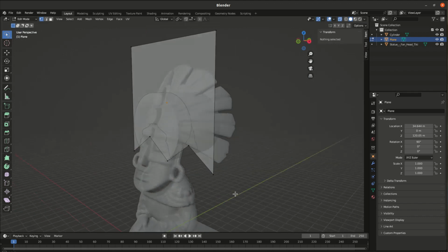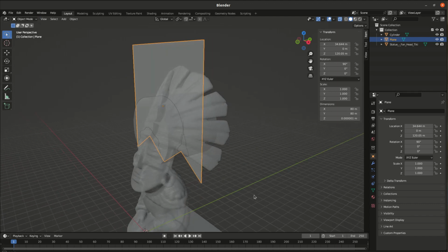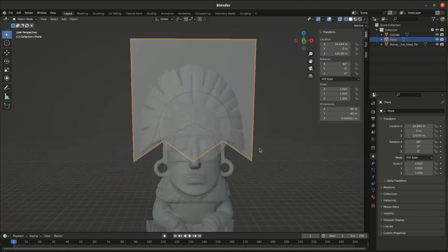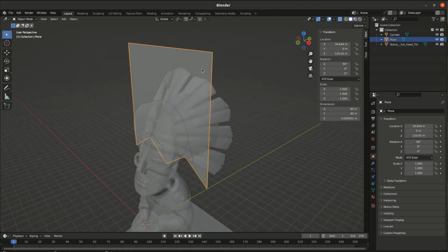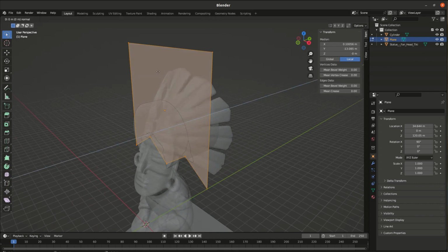Now, let's see. This is the object, the plane now. Okay, now we go to 3 to look at the model. We need to extrude it in a way that it can be inside this one. So we need to extrude it around 38, let's say. So I can select the surface here and extrude it. Are we in the edit mode? Not sure. Okay, Tab. Okay, back to edit mode. We select here, select it, extrude with E for 38.